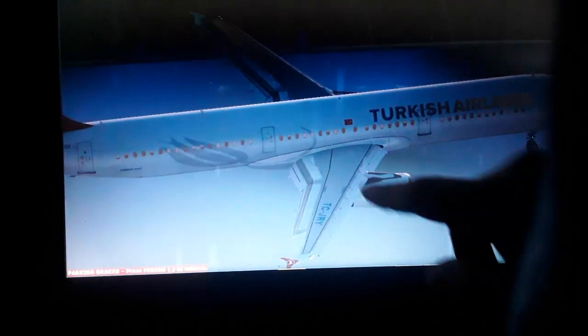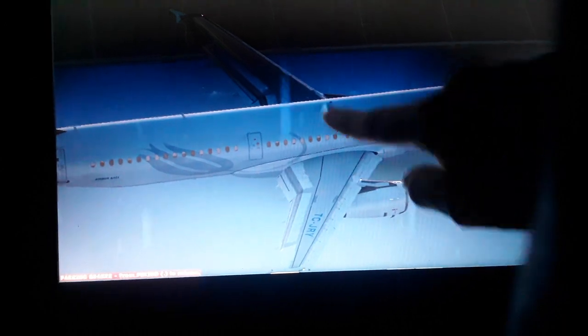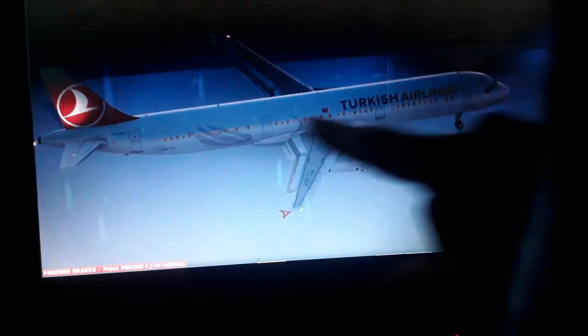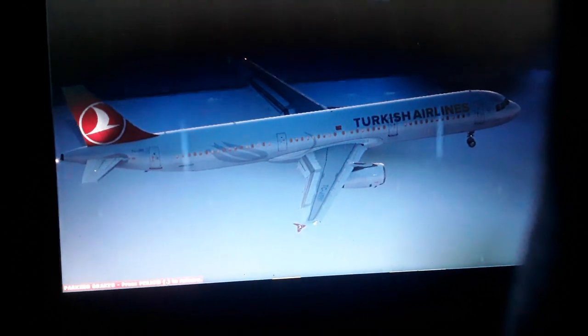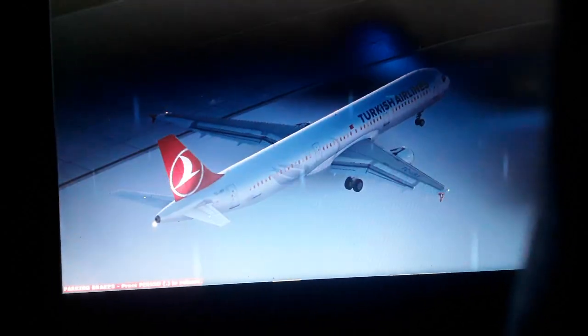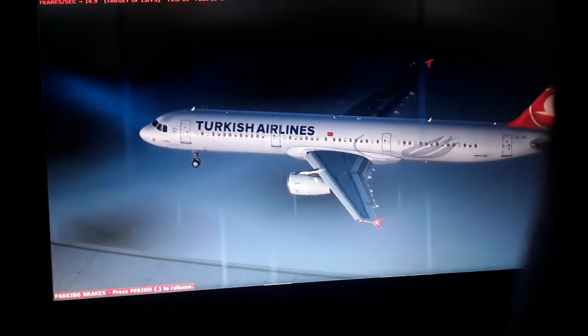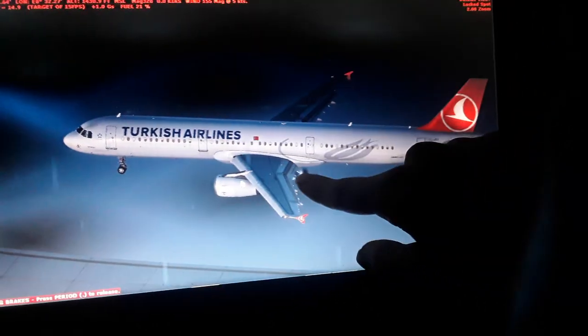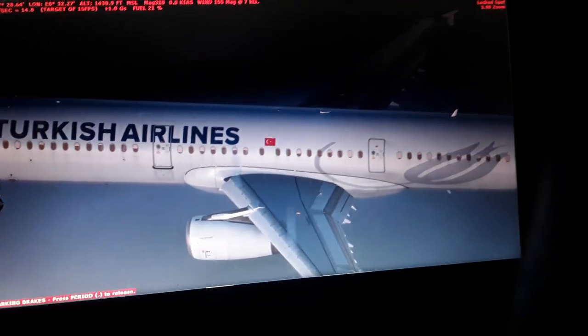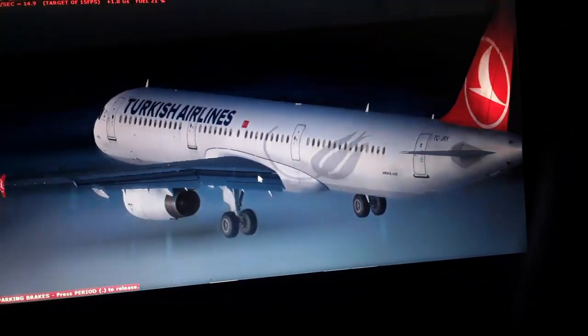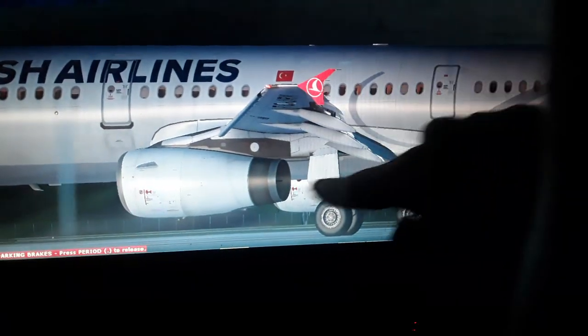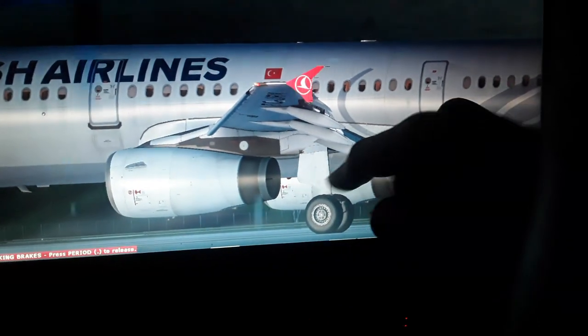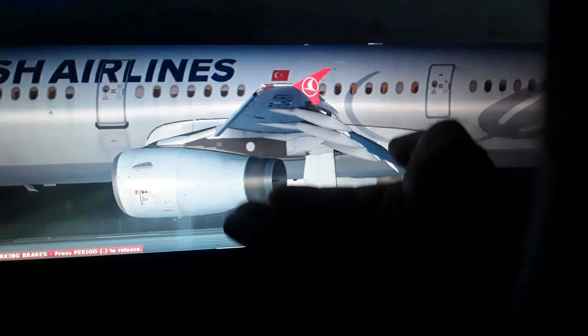So it's also where the position of the center of gravity is located for most aircraft. You can shift it forward or aft of this position by shifting passengers and cargo and fuel inside the aircraft. You can see we have the leading edge and the trailing edge, the airflow of the air mass. So you can see the bottom surface of the wings is more flat, generally speaking. So as the aircraft accelerates for takeoff, the airflow moves slower below the wing, so we have higher air pressure below the wings, which lifts the aircraft up into the air.